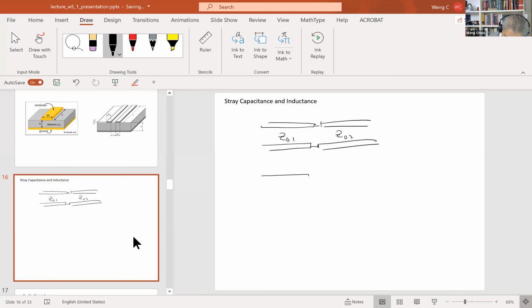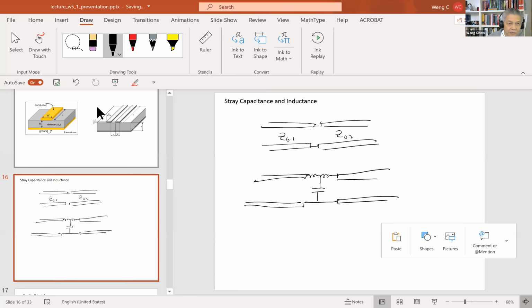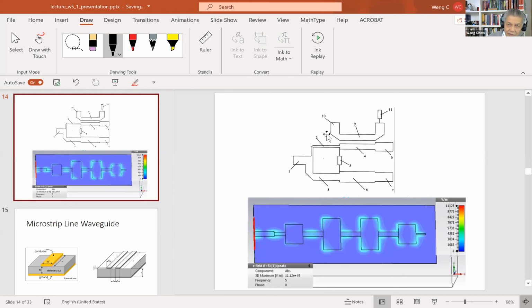Usually what you need to model a junction is to put in some circuits in between to model the junction. Because when you have a junction like what I've shown you in the previous picture, there are excess charges, and there might be constricted current flow that produces excess magnetic field, and that can give rise to excess inductance and capacitance at the junction.